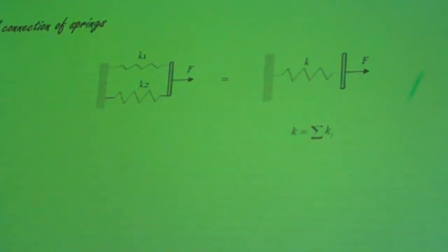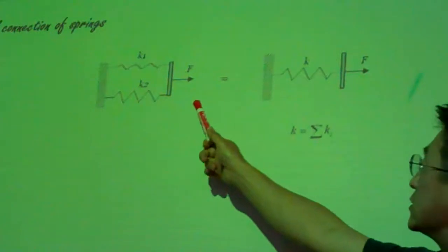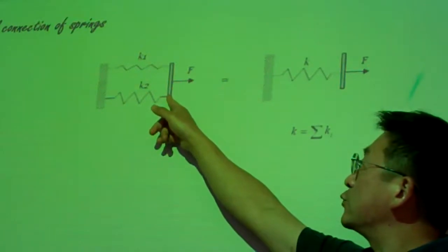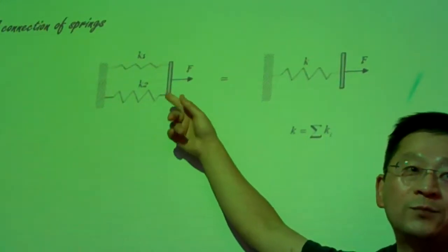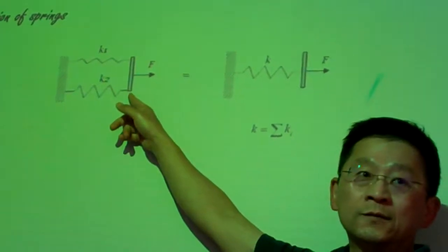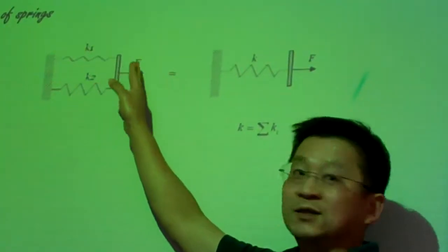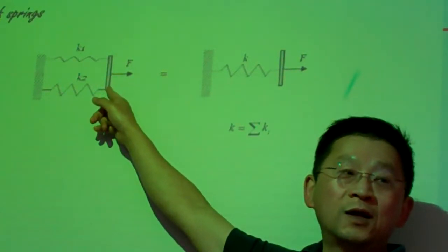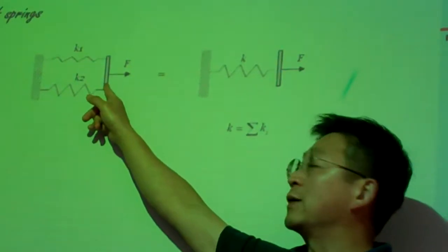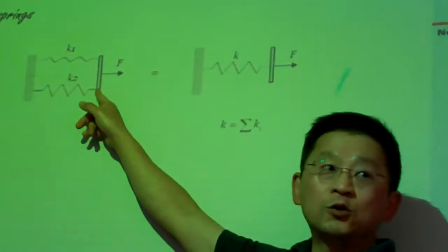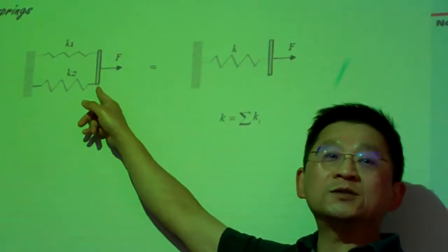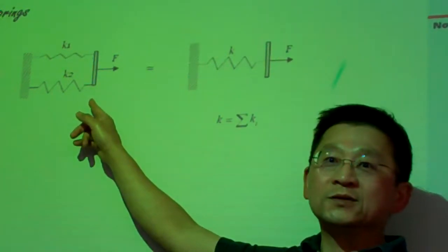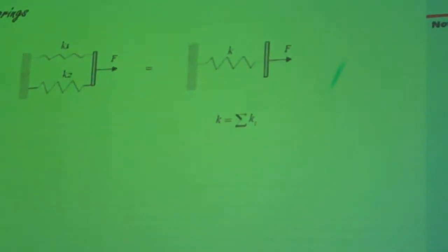The mathematical description is this. We have K1 and K2 connected through a rigid plate, which has no mass. This is simply a notation for connecting the two springs together in parallel. Assuming the plate is rigid means no additional elastic constant is considered from it. We consider the plate to have no mass, meaning it contributes nothing to our vibration analysis.